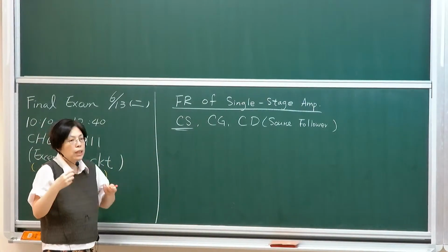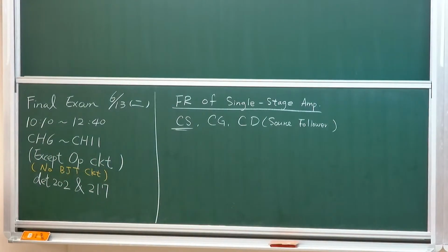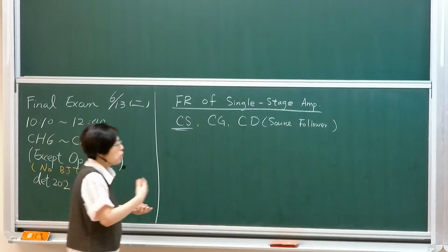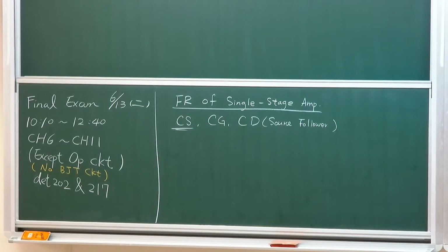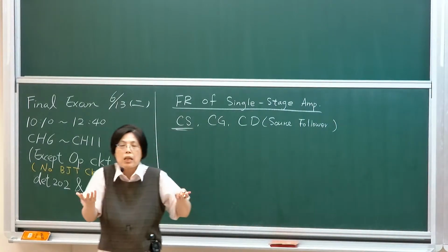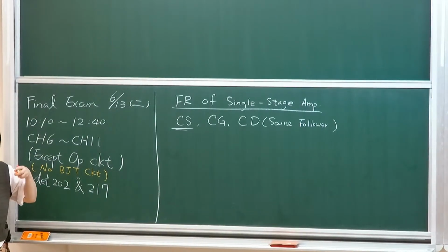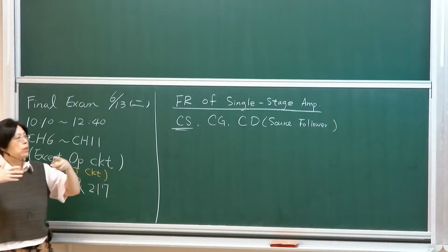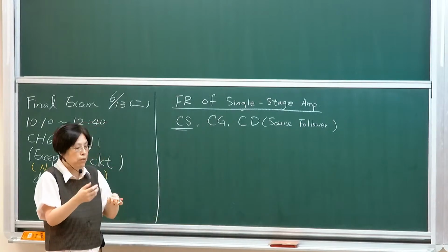I'm going to focus only on the impact of parasitic capacitance now, so we're only looking at the high frequency domain. Those are the parts that we have not yet discussed. For low frequency, those are external capacitances, and they mainly have the same effect on each one of the stages. The main difference among these three types of architectures is the parasitic capacitance, the impact of the parasitics.